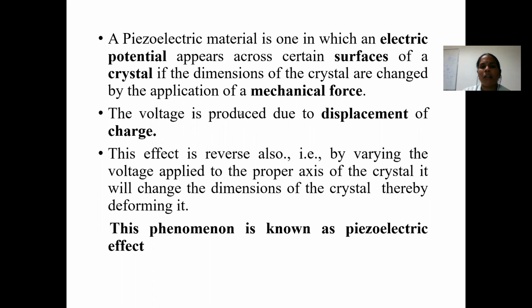A piezoelectric material is one in which an electric potential appears across the surface of a crystal if the dimensions of the crystal are changed by the application of a mechanical force. The surface of the piezoelectric material changes its dimension on applying the mechanical force, which causes an electric potential across the terminals. The voltage is produced due to the displacement of charge, which causes the potential difference.